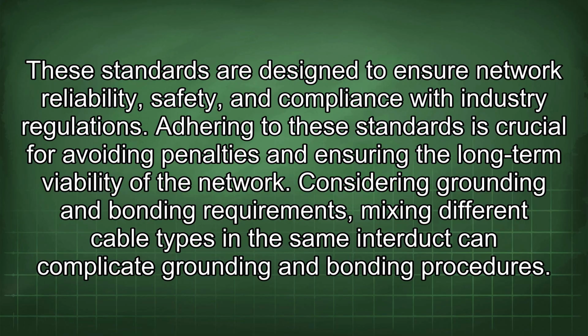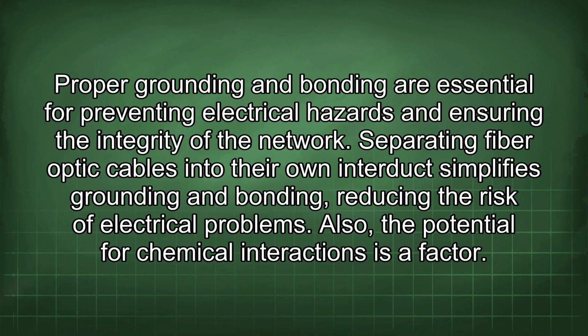Consider grounding and bonding requirements. Mixing different cable types in the same interduct can complicate grounding and bonding procedures. Proper grounding and bonding are essential for preventing electrical hazards and ensuring the integrity of the network. Separating fiber optic cables into their own interduct simplifies grounding and bonding, reducing the risk of electrical problems.